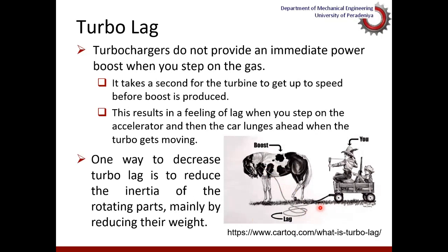Now, with modern manufacturing technologies and so forth, the compressors and the turbo units were made using highly lightweight material, reducing the moment of inertia of the rotating parts and the weight of the rotating parts. And accordingly, the turbo lag also was reduced significantly in modern day technology.